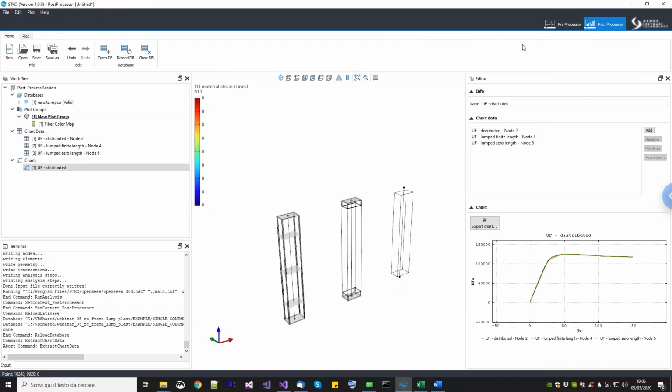Okay, so what is the difference between the elastic beam and the elastic force beam column element? The only difference is that the elastic beam is a displacement-based element, while this one is a force-based element. Now, in our case, at least in the elastic response with a constant cross-section, there is no difference because they are elastic and they have the same material properties all along the elements. So basically, they are the same. They don't give any different result.